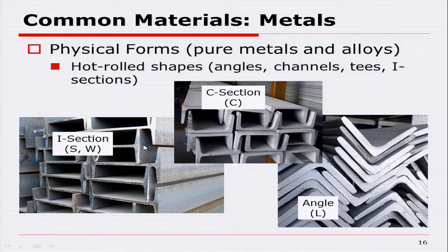I sections come in a variety of sizes. We use I sections typically in high-rise steel construction. In low-rise steel construction, by the way, we don't typically use I sections. We actually make our I sections out of plate, flat stuff. And the reason is that for lower rise buildings, we typically want to have the perfect shape for the loads that we're seeing. And for people that are familiar with mechanics of materials, understand that the higher the bending moment, typically the more depth you want in your I-beam.